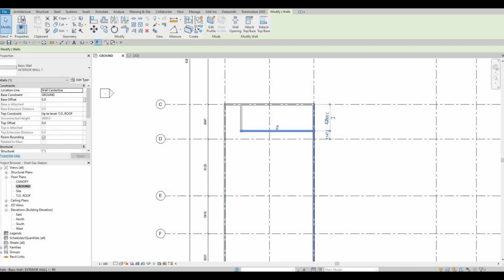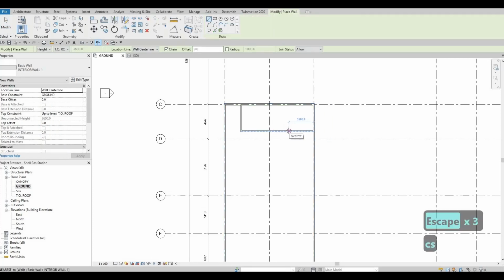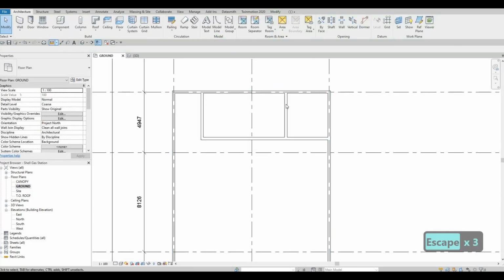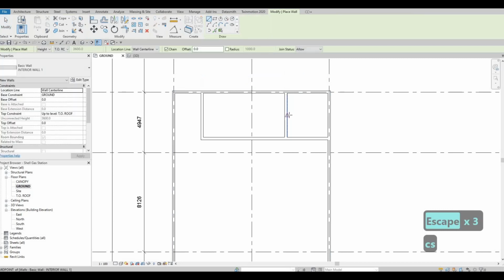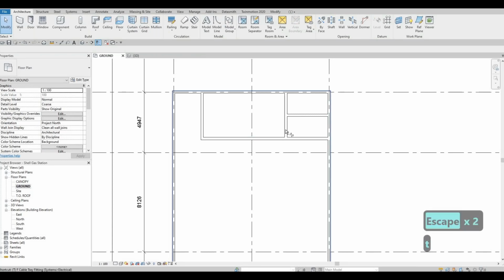And then this one is around 3800 from that wall, from that grid line. And then I'm gonna open this up because we're going to add another room right here. This room is around 3500 from this wall, so you can see 3500 from this grid line. And then again, we're going to have a wall right here, and then what we're gonna do is TR, trim and extend.